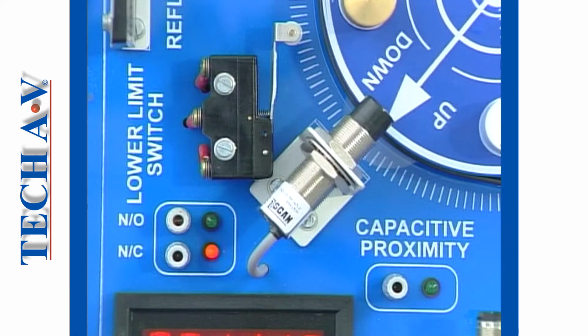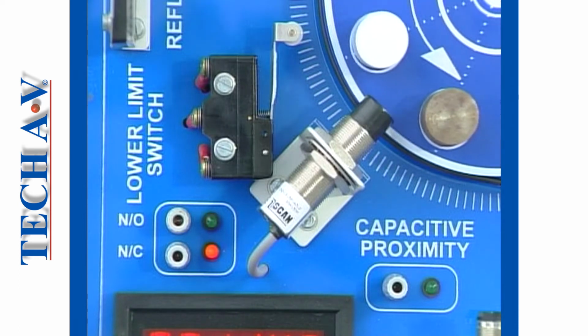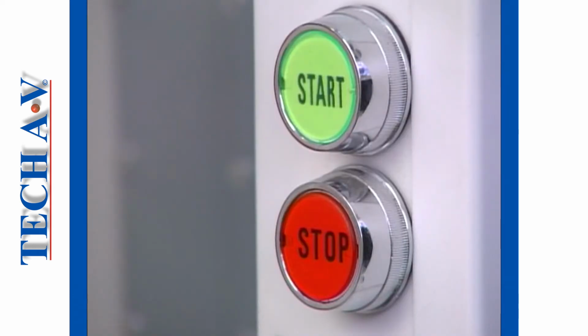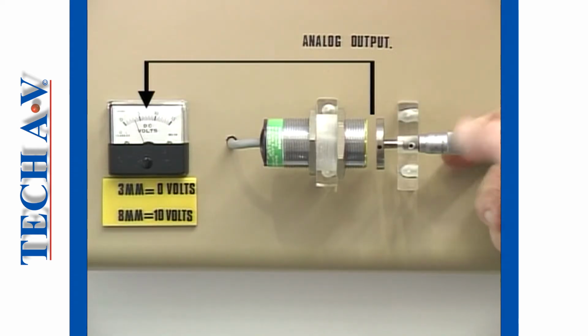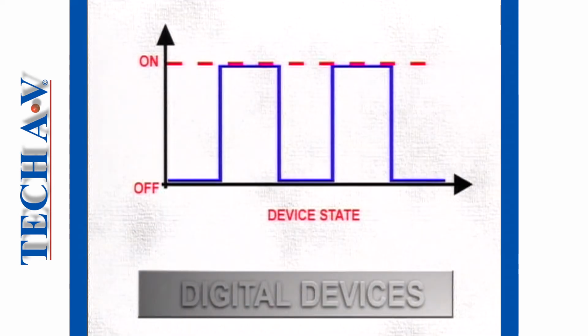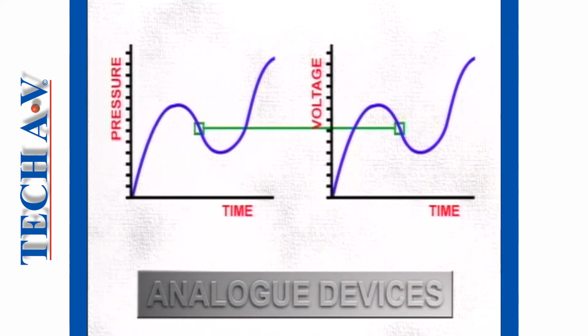Before we begin this module, let's review the important points we learnt about in Module 2. Firstly, we discussed input devices and how they gather information. We identified two specific types of input devices, namely digital and analog. We explained that both types are classified as information-gathering devices. However, digital devices send messages as simple on-off voltage signals, whilst analog transducers transmit dynamic output voltage signals which change according to the physical condition they're measuring.